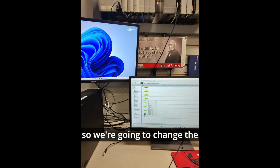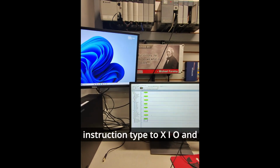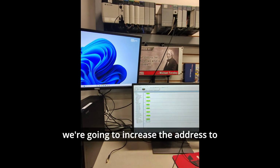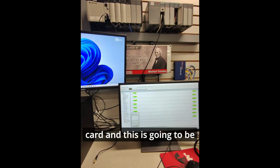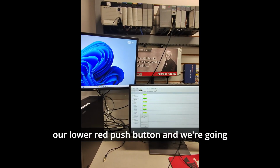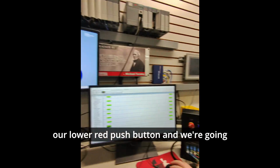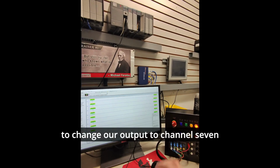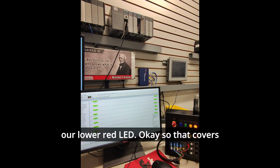So we're going to change the instruction type to XIO, and we're going to increase the address to channel 7 of our input card. And this is going to be our lower red push button. And we're going to change our output to channel 7, which is going to be our lower red LED.